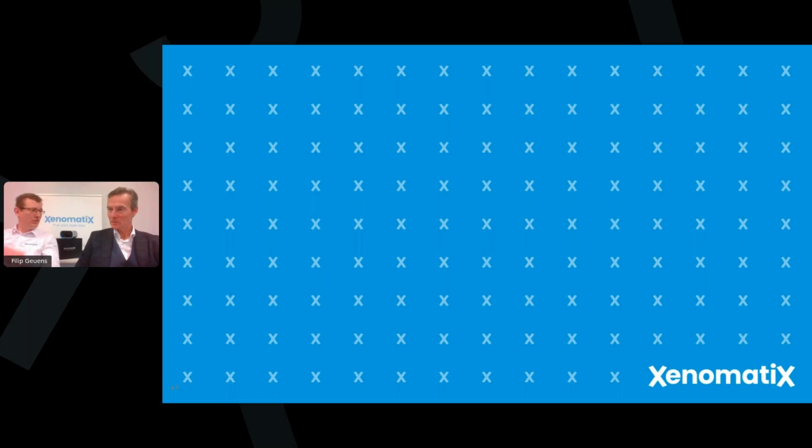And as we saw, within one frame, and that's the entire power of the advanced reflector handling, the neighboring pixels are not affected by the reflector itself. Correct, which is of course the strength. The anti-blooming. Yes. So if you have an application or a use case where you expect a lot of reflectors, for example on the street where there are a lot of cars, then we certainly advise you to buy the advanced reflector handling option.